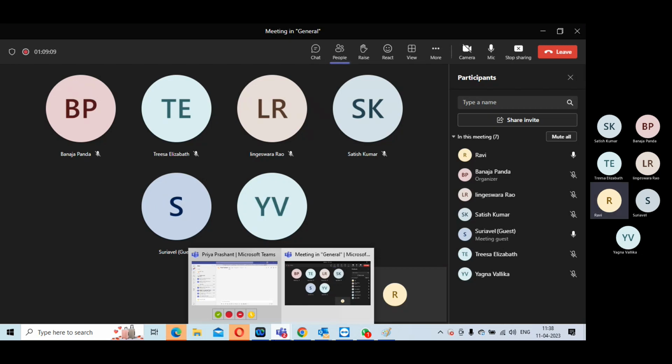So you have to address this. If your CTS is seeing somewhere that is going far off and unable to balance, or your clock is trying to take the longest route, you can look at, from a clock point of view, whether I need to create multi-point CTS or that module has to be pushed down, because of which I have to make some floor plan changes, or I have to create a move bound, because this logic is getting spread.